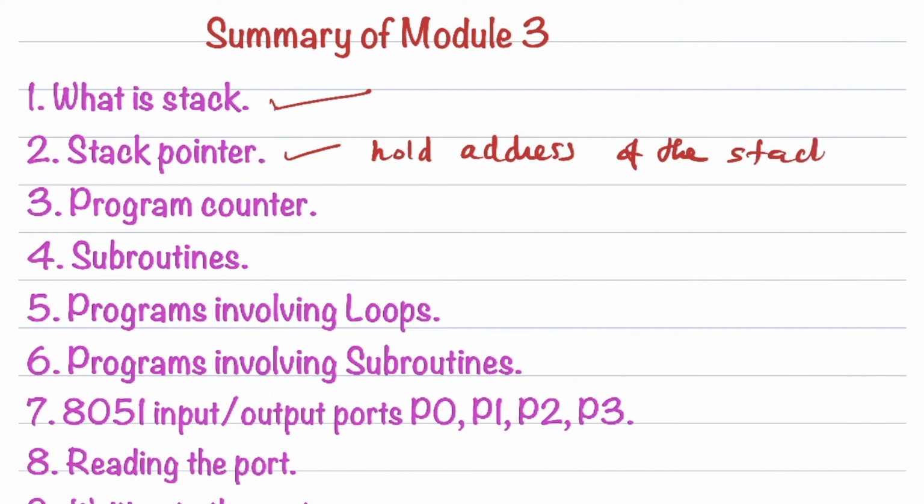By default, the stack pointer value is 07, and hence the stack memory will start from internal memory location 08 onwards. That's the default case. This is what we have seen about the stack.